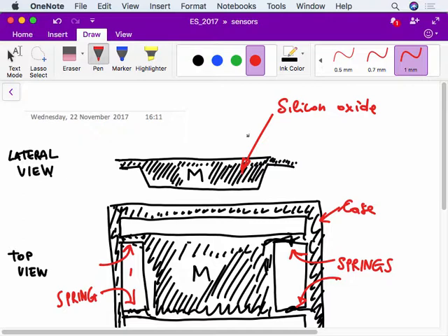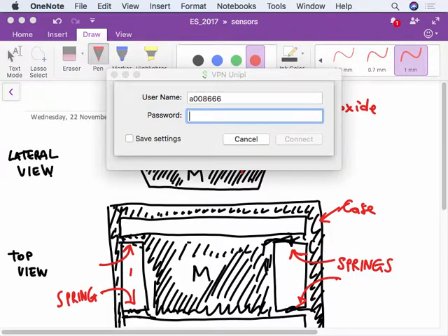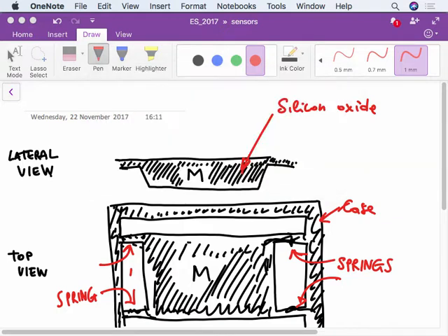And actually, the damping term is simply provided by air, because this whole thing is done in air. So basically, if you put the mass into oscillation, at some point, because of attrition with air, the mass stops. Okay. So this is how typically it's done, and this is something that in practice is less than 1 millimeter in both directions, in the X and Y. It's a very small thing.